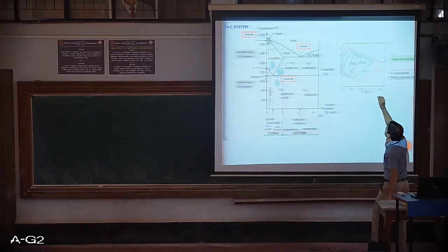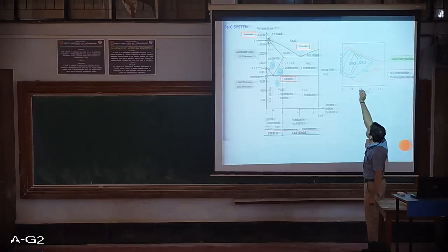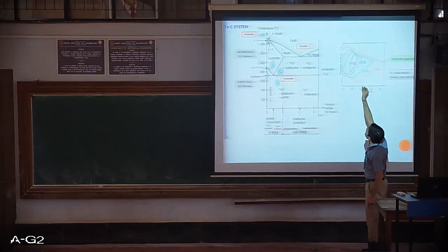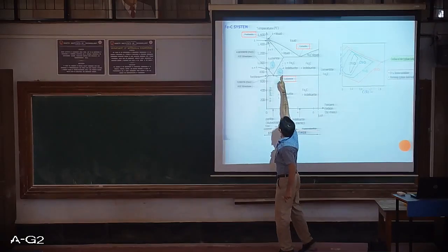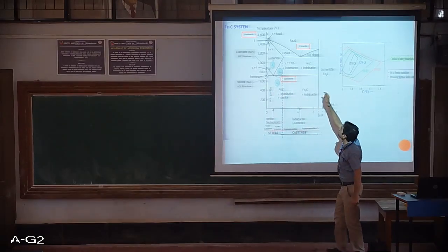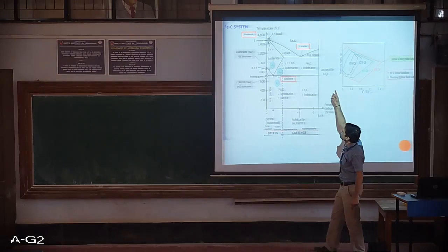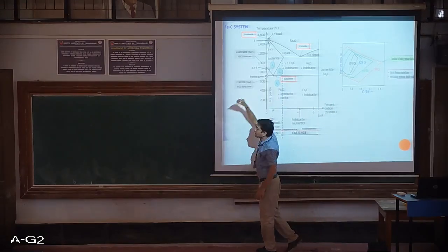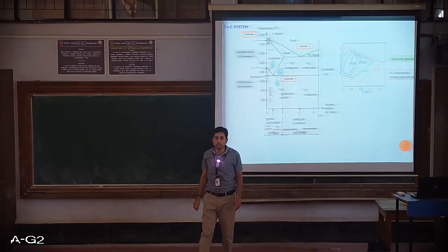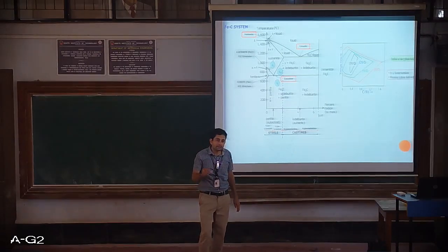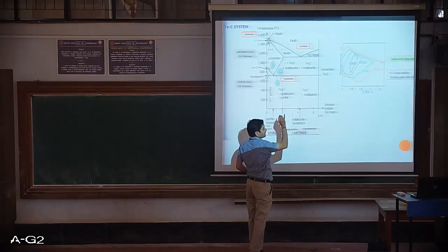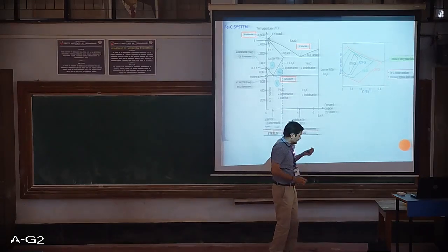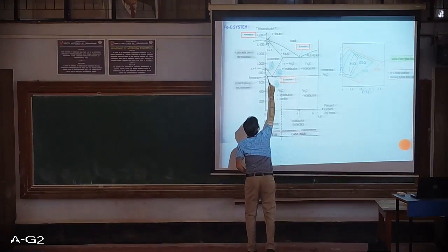If you see this graph, this is the carbon percentage against temperature. As you go on increasing the alloying element percentage from 0 to 15%, you will see that a rhombus kind of shape goes on shrinking more and more, because of which, in other words, the ferrite phase becomes more and more stable in the steel. This is what happens if you add ferrite stabilizers into the steel. I hope you have understood it. You see that this is the iron carbon diagram, and this is the region where the ferrite phase is present.